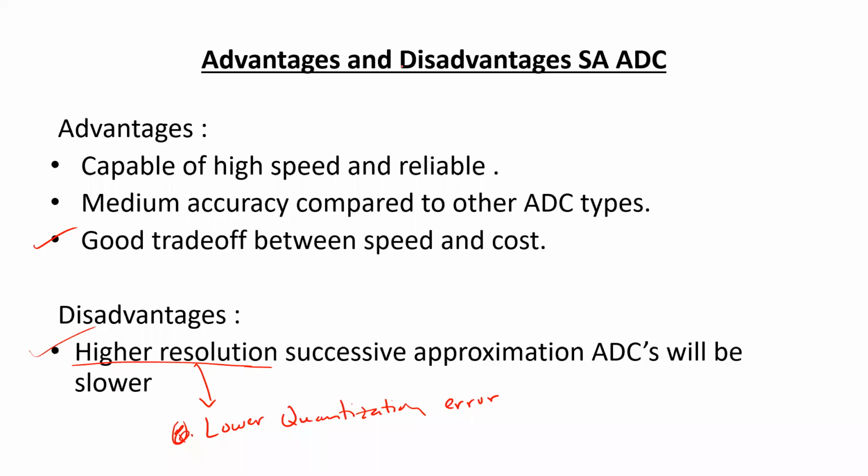Well, normally they are used for testing purpose. Suppose you are manufacturing a low range resistance. Suppose you want to check how close the value of your resistance is to the standard resistance. So you have three arms which are fixed, right? Suppose in one of the ratio arms the two resistances are fixed, and in the other arm you have a variable resistor. So that variable resistor is actually going to work as a standard resistor.